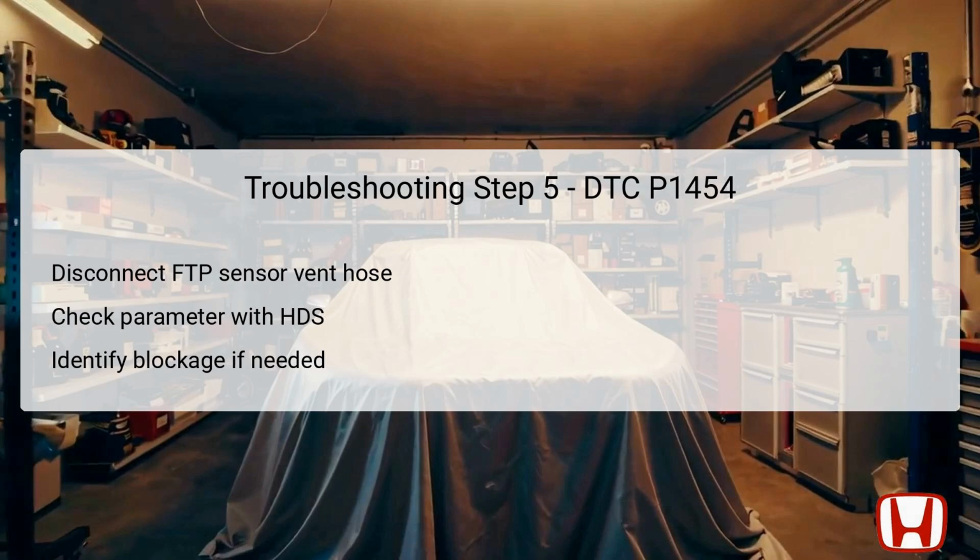the system. Conversely, discovering a blockage means that the vent hose or adjacent components require cleaning or replacement to ensure proper ventilation and functionality of the EVAP system. This step highlights the importance of thorough visual inspections and functional tests throughout the troubleshooting process for effective diagnostics.